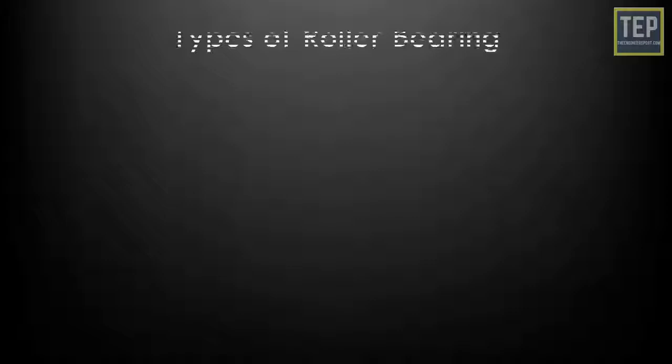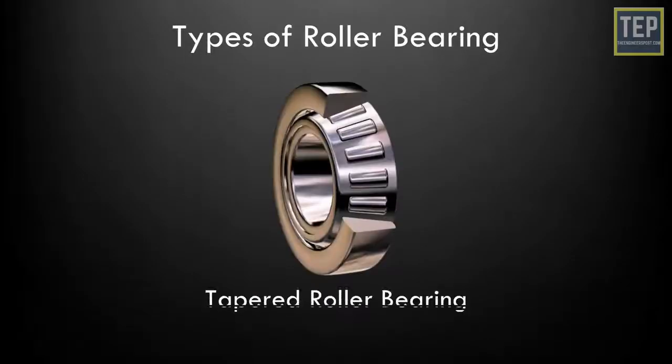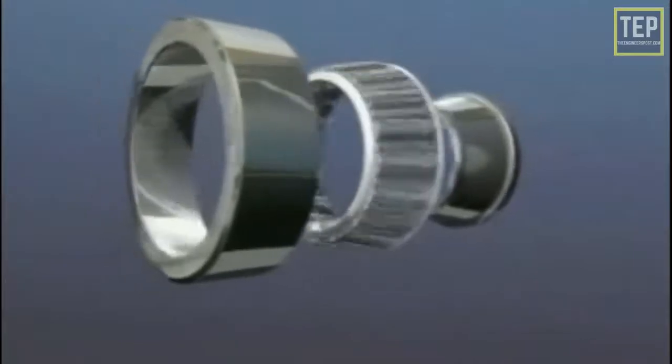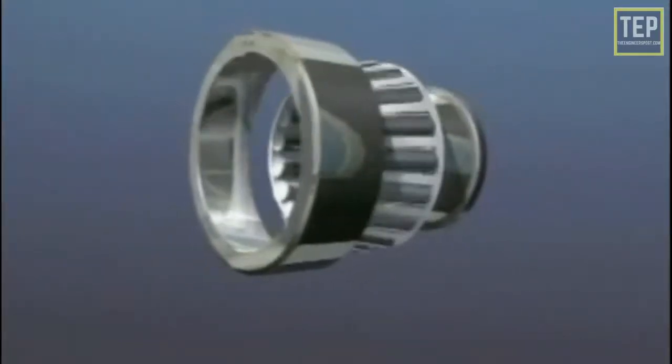The tapered roller bearings contain sections of a cone as a load-carrying element. These rollers fit between the two races that are also sections of a hollow cone. If the races and the axes of rollers were extended, they would all meet at a common point. Tapered roller bearings are designed to handle higher axial loads besides radial loads.